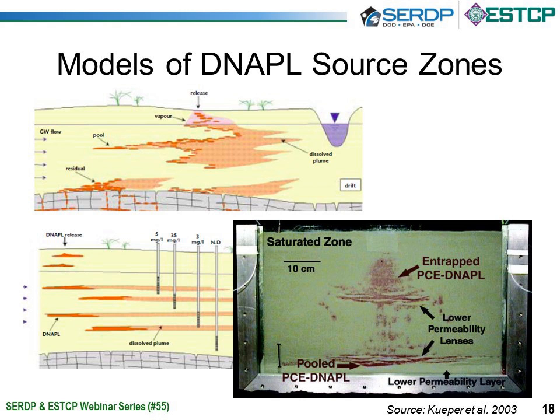So here we are 30 years after the term DNAPL was coined by Stan Feenstra. Before 30 years ago, we didn't really know that there were contaminants like chlorinated solvents, PCE and TCE, that when spilled would migrate to sometimes great depths, even below the water table, where they could be trapped in ganglia and dispersed in fairly heterogeneous fashion in the subsurface.